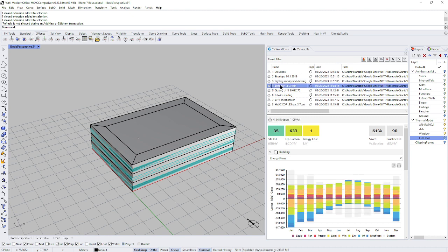What does this tell us? Well, first of all, that our envelope is less important than our air tightness in a building like this. Why would that be true? It's because air volume is having a larger effect than surface area of our walls, because this is a really large building. If you don't get that, don't worry about it. I'm just going through and showing you how we're optimizing this envelope before we then look at peak heat loads.